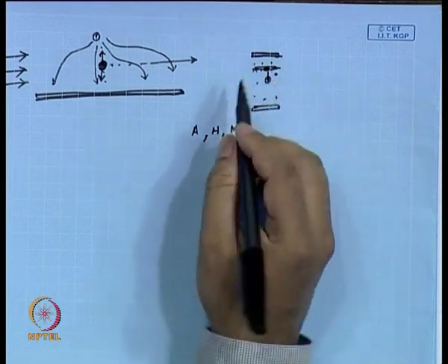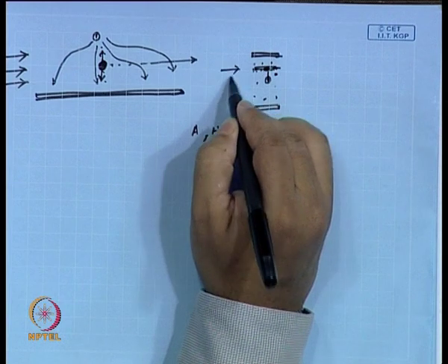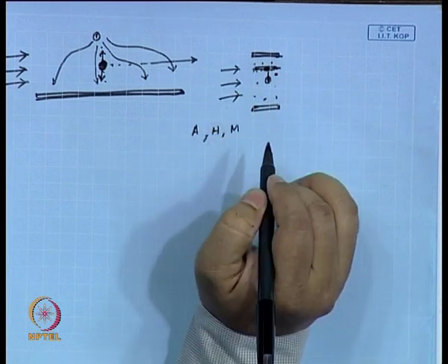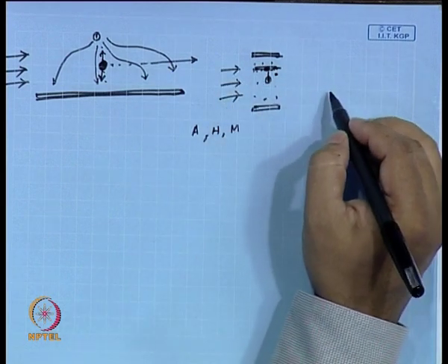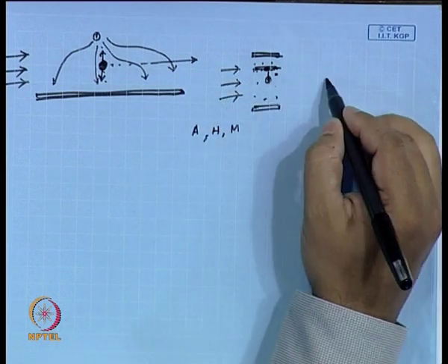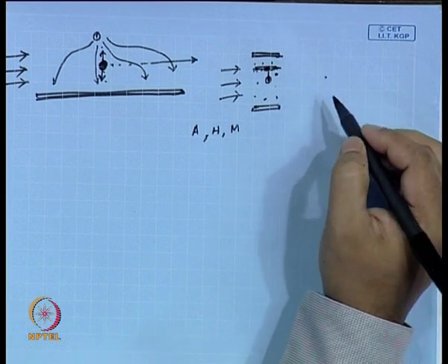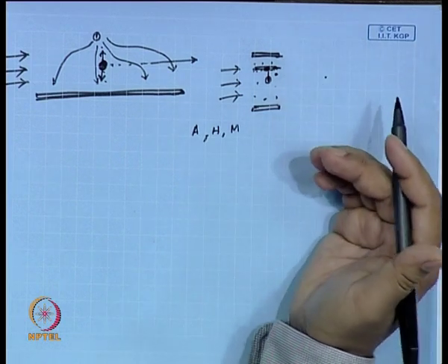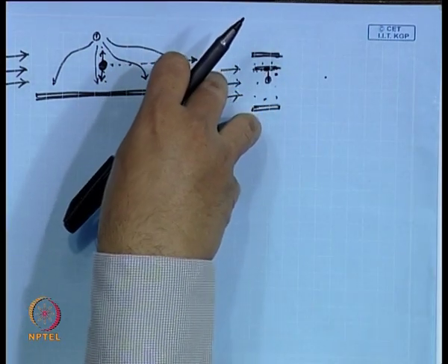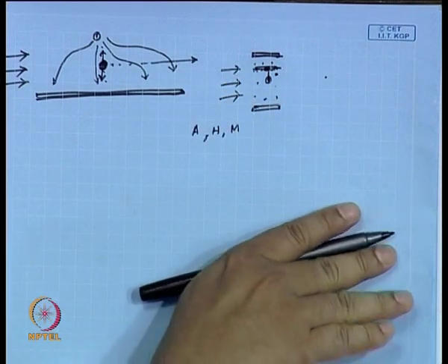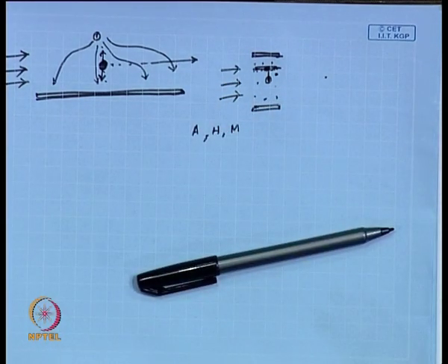On top of it, if you apply a laminar or parabolic velocity profile through this, then at the outlet you will be eluting one layer at a time, first the central layer, then the other layers. If you have a pre-calibration done, that means if you had a known sample going into it and you know when the components are eluting, then by looking at that calibration plot, you can compare with a real life sample and say that this real life sample must be